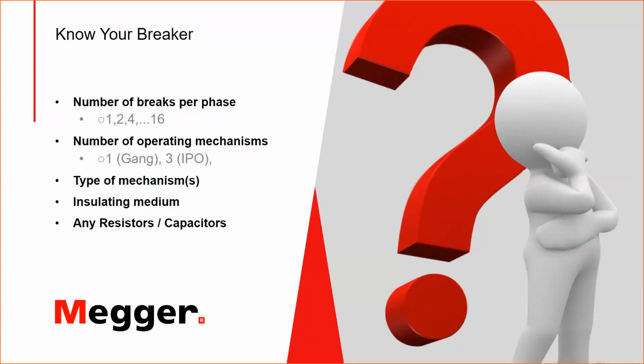What is the insulation media, and what do you need to consider for this insulation media when you want to do testing? For example, in a GIS environment I will handle the test differently than in AIS, or air insulated switchgear. Do you have any resistors or capacitors, pre-insertion resistors or post-insertion resistors, or any grading or shunt capacitors? And how can I deal with these components? It is very important to know this to be able to test any type of circuit breaker.